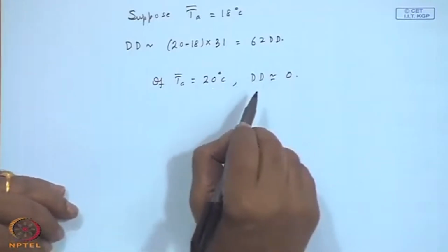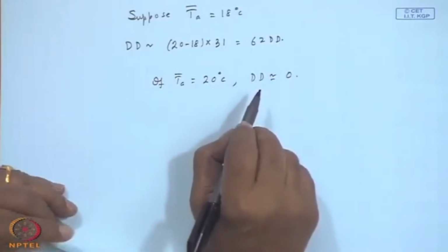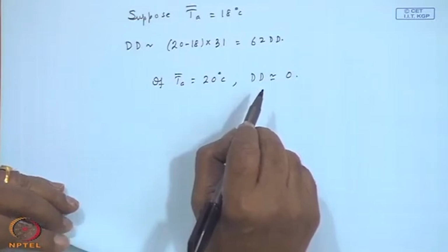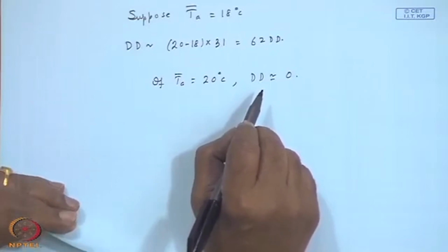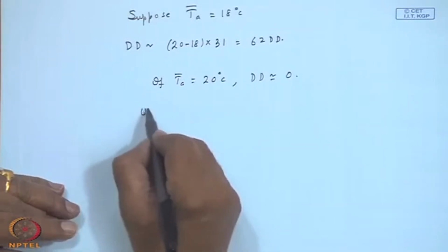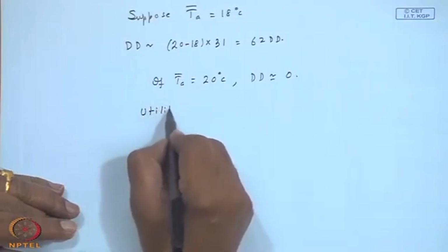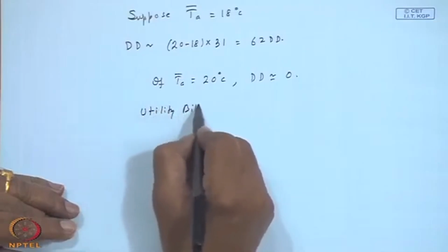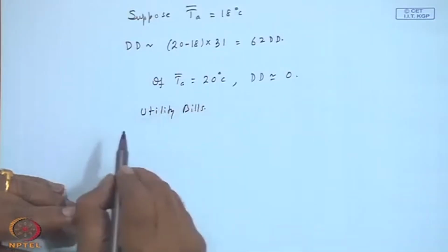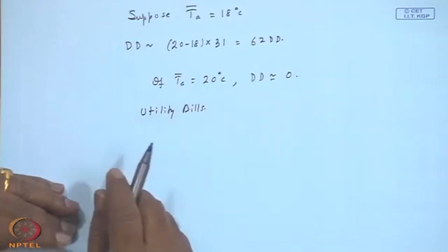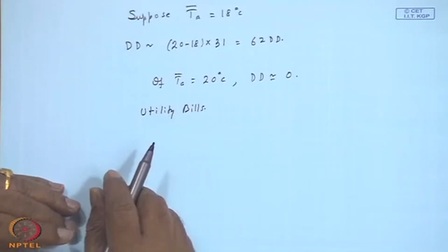So, for degree days calculation, the best thing is if you have the hourly data file, one can compile it or depend upon the utility bills. So, if heating required so many kilowatt hours of energy and you paid so much, that much is the space heating load.